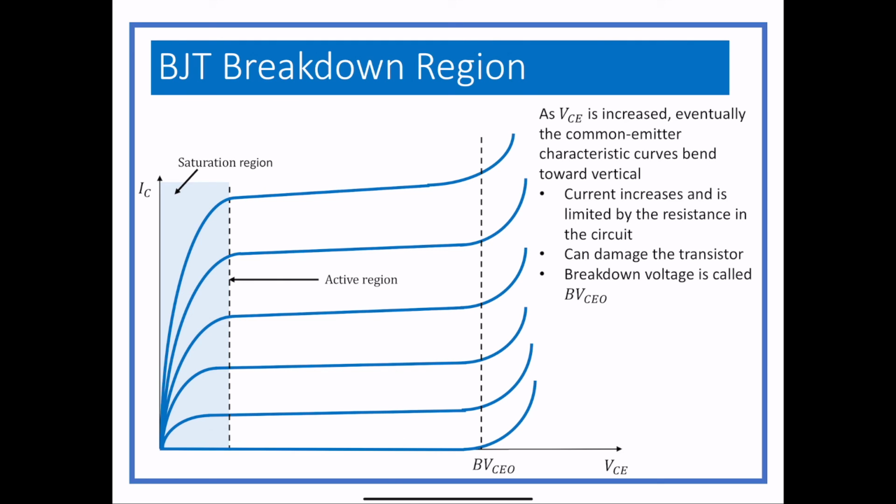Yes? Is there some type of BJT that's like a Zener diode that's meant to be operated like that? I don't see how you could, because you have to have the junctions biased in a certain way. That would end up making it upside down, or it would basically put it into cutoff mode. So it doesn't really work quite the same way.